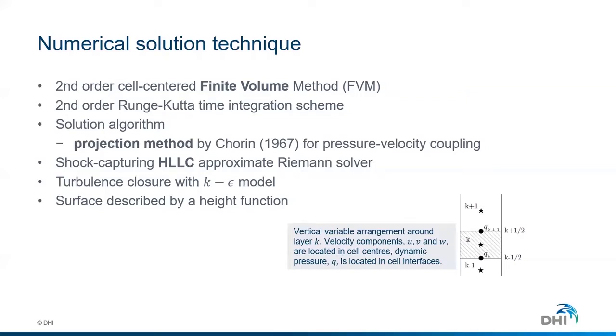Then we have implemented the software with a shock capturing HLLC Riemann solver, allowing us to reconstruct the intercell fluxes in areas with discontinuities in the surface elevation. A case where this will happen is when we see waves shoaling up and breaking. In those areas, we will introduce discontinuities in the surface elevation, which is handled by this HLLC Riemann solver.